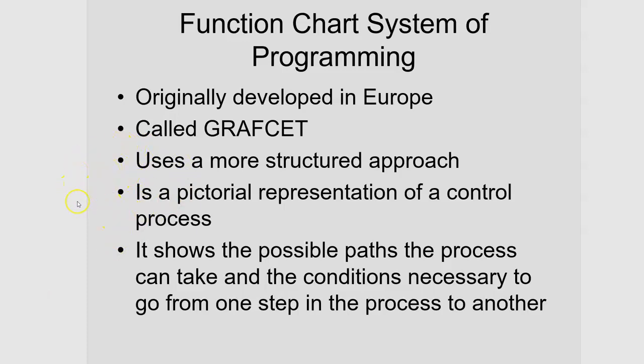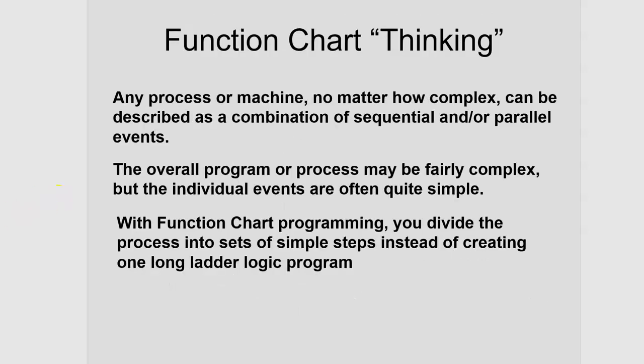This is nice. It's a pictorial representation of a control process. So it still uses elements from your regular ladder logic, but you add structure to it. And by structure, what we mean is it's more like flow charting, and each shape in the flow chart will be represented with some kind of relay ladder logic. So again, we'll go into that. This idea of function chart thinking.